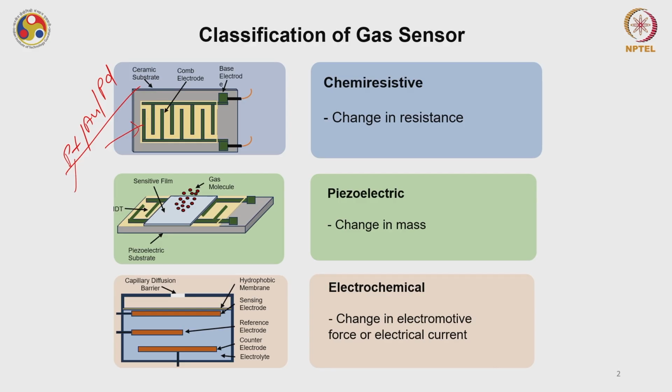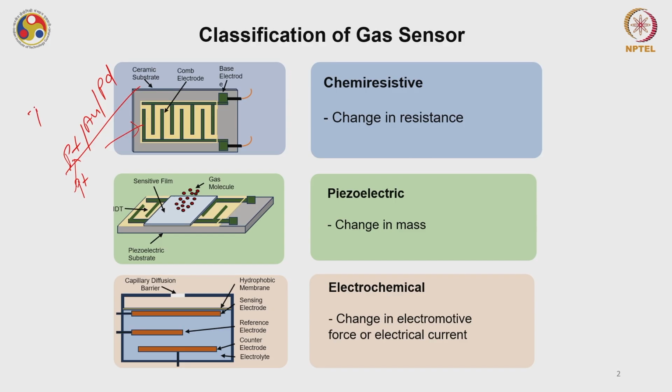In that case, you have to be very careful, as platinum does not have a very good sticky nature on Si/SiO2. So in that case you have to look for some other material, like titanium. Titanium has a very good adhesive nature on Si/SiO2 substrate.